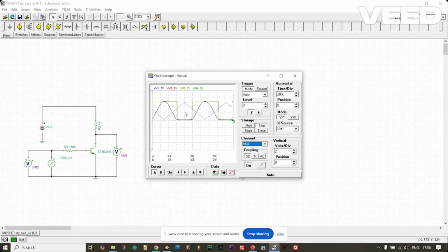So that's the advantage of the MOSFET over the BJT. It can be switched over fast, because it depends upon the voltage. That's why the behavior is like that. So this is the waveform. It turns off to on suddenly, and on to off suddenly, unlike the BJT, which goes gradually.